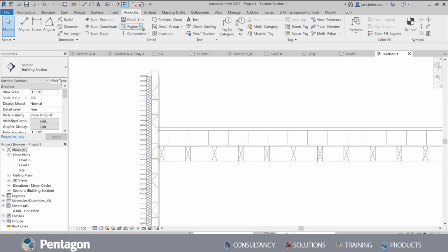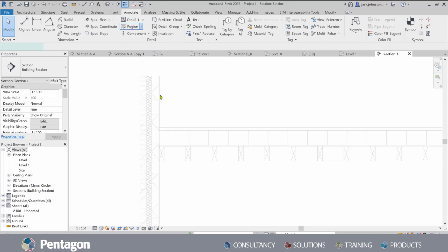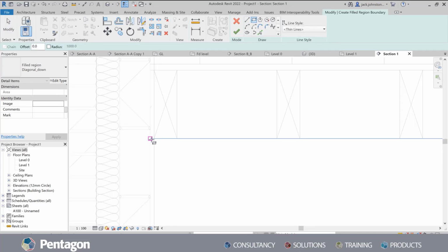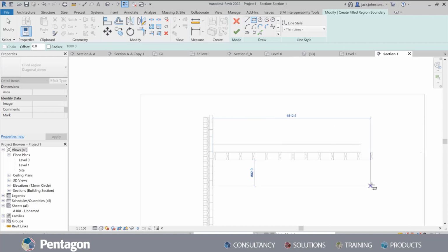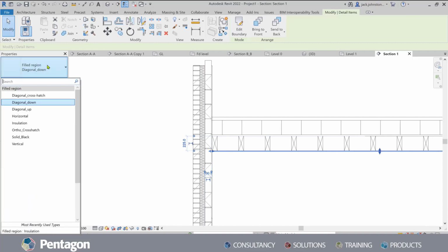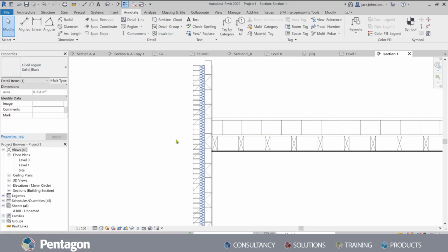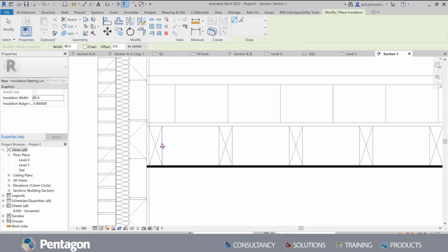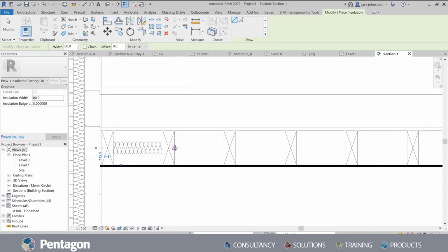Again, if I wanted to add in maybe some plasterboard there, what we can do here is just pull that across, don't care what size it is. Select this, 12.5. There we go. Solid black, there's our plasterboard. Maybe I want to stick in some insulation between the joists, or just to improve the U value of that roof.